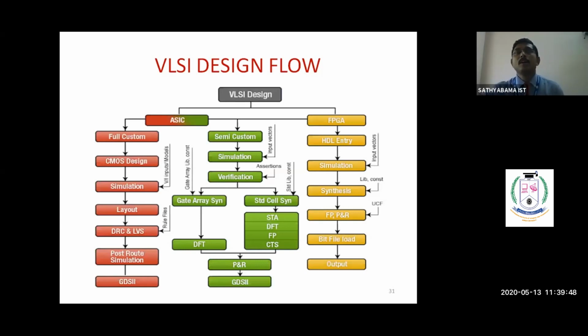So here the schematic is going to be developed. The schematic can be developed by using any logic, like static NMOS inverter logic or static CMOS logic. Any logic we can use to develop the schematic. Then after making the schematic, we go for simulation. As I already told, simulation is used to check the functionality, that means the logical functionality: whether the circuit has been designed as per the logic or not. We give some set of inputs, run the circuit and check the output. That is nothing but a simulation. Then after that we are going to make the layout.